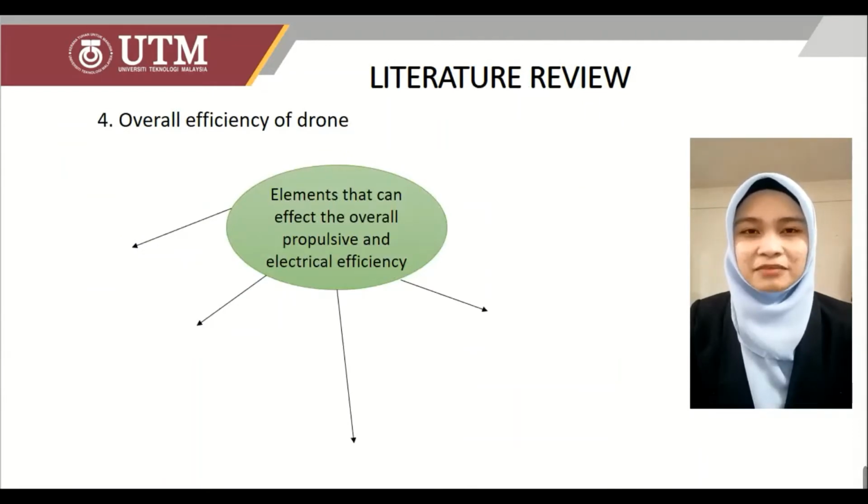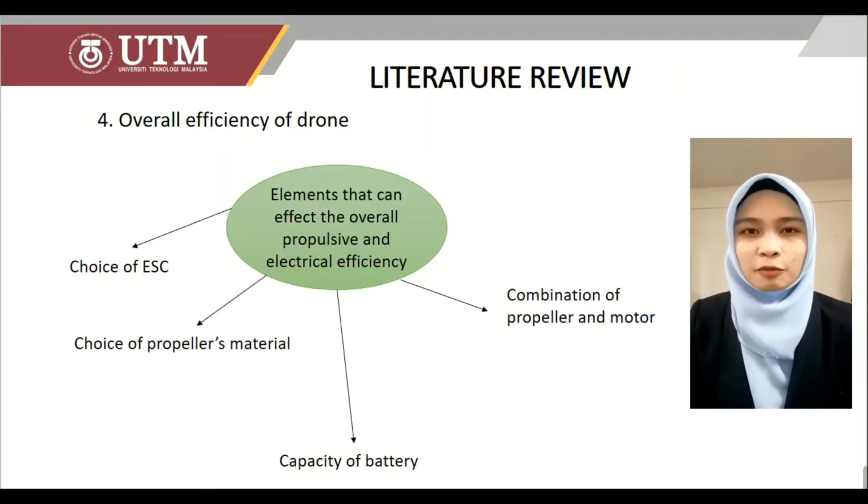There are several elements that can affect the propulsive and electrical efficiency, such as choice of ESC, choice of propeller's material, capacity of battery, and combination of propeller and motor. So for my project, I will focus on the combination of propeller and motor.